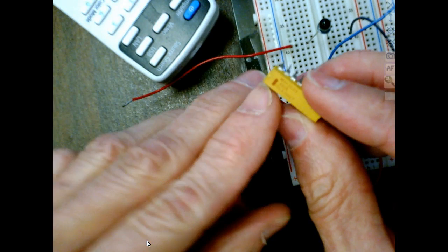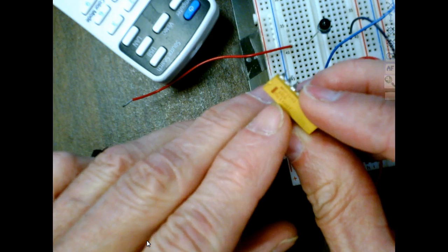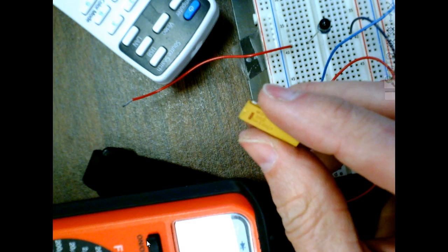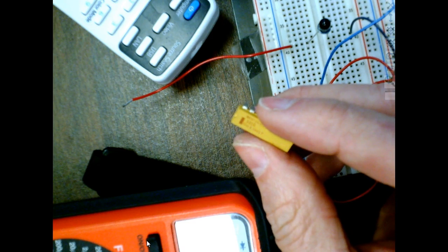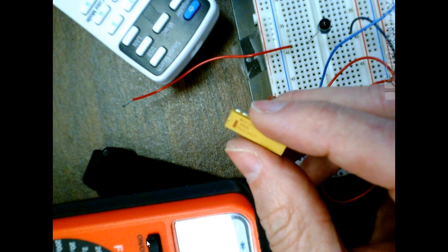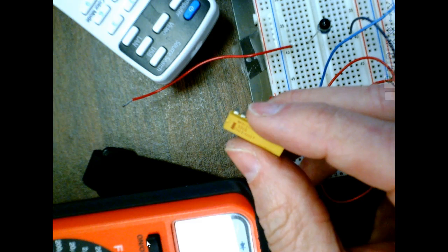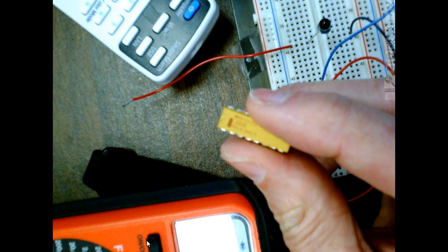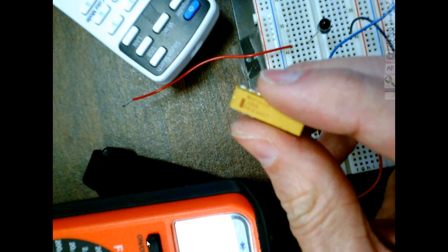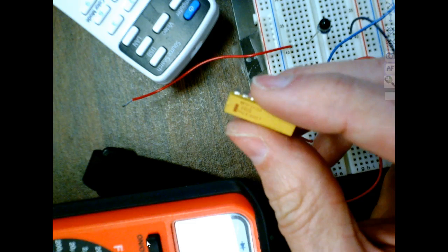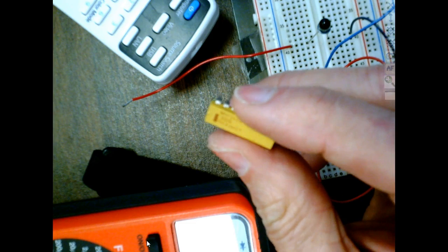The way this thing works, it's got 331, so it's kind of a color code, but it's not. If this was color coded, it'd be orange, orange, brown. So that would be 3, 3, and 1, 0. So this is another way they do it, where they don't give the color, they give the numbers. So this is 3, 3, 1. What would that mean? 3, 3, and 1, 0. That's a very common way of doing these resistor packs.